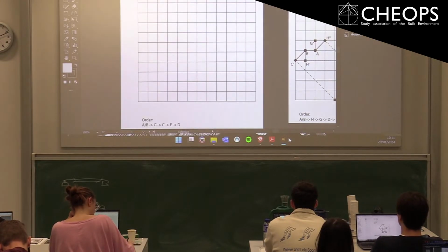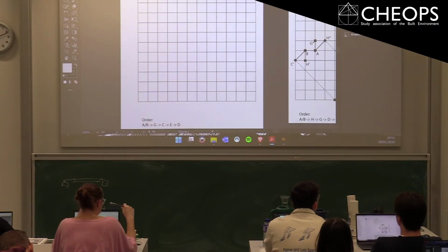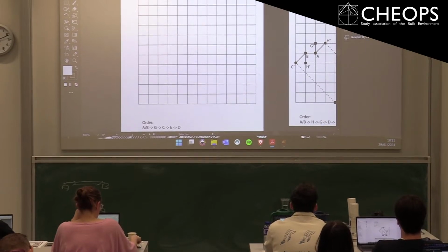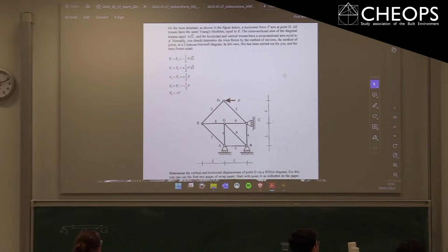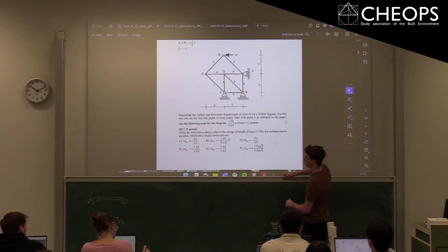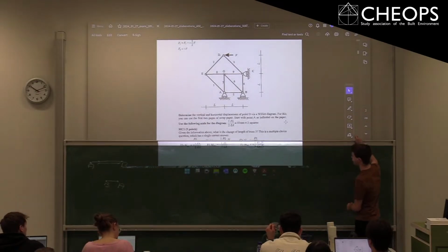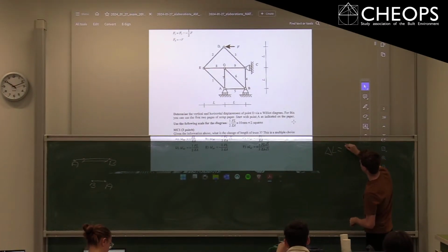Yeah, and for these ones, we're going to go through here. Let's see, because I'm not going to do this on the blackboard. First, you need to be aware that these have 2 ways of being asked. The first one is that you get the forces and you have to calculate the elongations yourself, right? So you all know that equation of the elongation, that's equal to FL over EA, right?